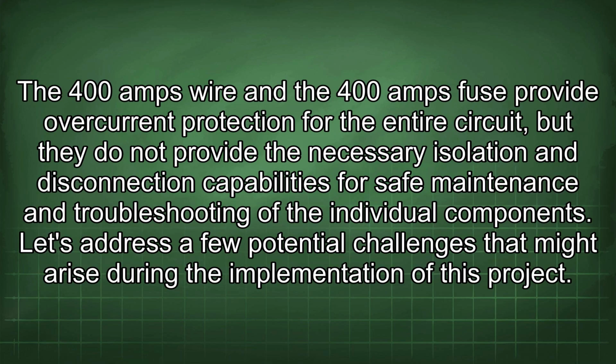The 400 amps wire and the 400 amps fuse provide overcurrent protection for the entire circuit, but they do not provide the necessary isolation and disconnection capabilities for safe maintenance and troubleshooting of the individual components.